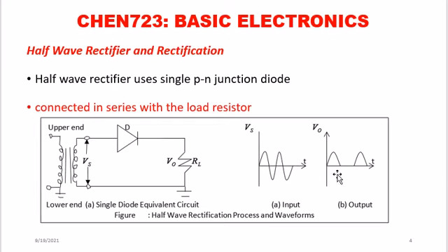Here we are using a single diode to achieve that, and that is why we call it half wave, because it is a single diode, you will see. When you supply your AC to this transformer, the function of the transformer is to reduce the voltage. Mostly we reduce it to around, let's say, 12 volt, 15 volt, 9 volt, depending on what I need. When the positive comes here, it will forward bias this diode, and the positive will flow through the diode to the load. But in the negative half cycle, this will be negative, and therefore the diode will be reverse biased. It will not conduct. It is blocked, nothing flows.